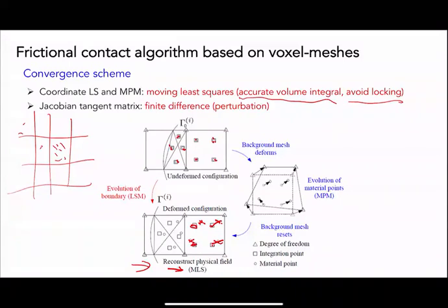The advantage of using the Gaussian points is that you can control the accuracy of the numerical integration. For example, for a four-point or quadrature element, you can control the order of accuracy easily by projecting the material point information back into the standard Gaussian point locations.